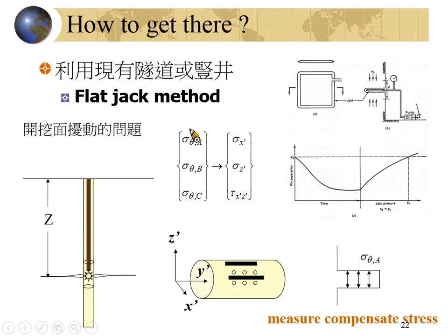This process could damage the rock surface. The other will be the stress concentration. Because you have a stress concentration that makes the high deviatoric stress, you will influence the rocks surrounding the tunnel wall. So this will be the influence of the disturbance.